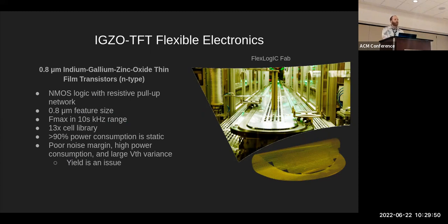Third, most power is static power. And fourth, and most important for this work, it has high noise margin and high variability, and therefore building anything with more than a few hundred gates is going to be extremely challenging. How do we build IGZO TFT microprocessors that meet flexible application requirements? To answer this question, we need to better understand the domain applications.